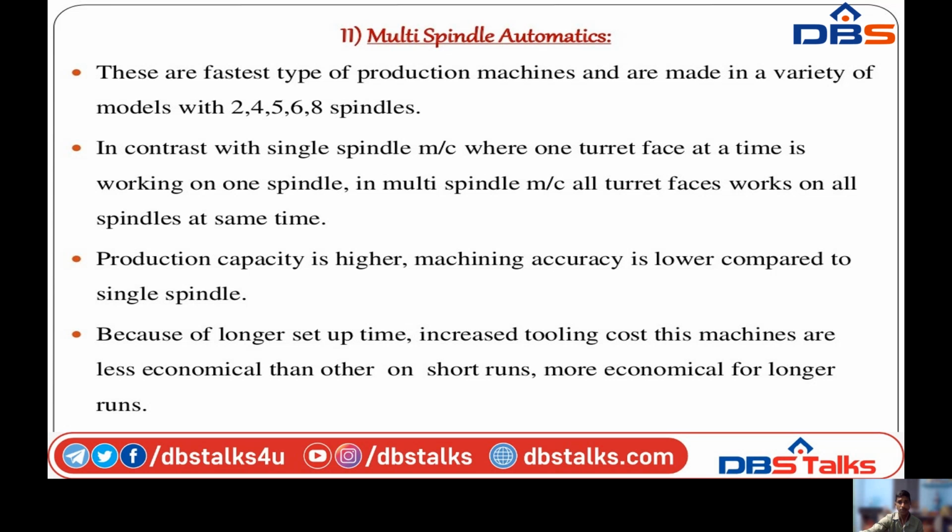What is the difference between single spindle and multi-spindle? In single spindle we are using only a single spindle, that means only one phase is working. When it comes to a multi-spindle automatic lathe machine, all spindles, that means all turret phases, are working at a time. Production capacity is very high and accuracy is lower compared to single spindle. Why? Because accuracy is